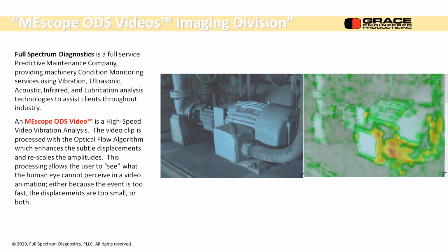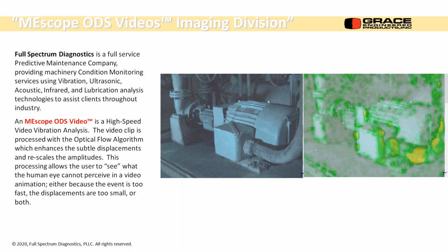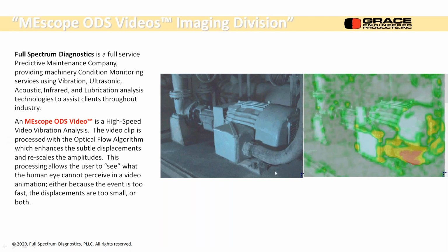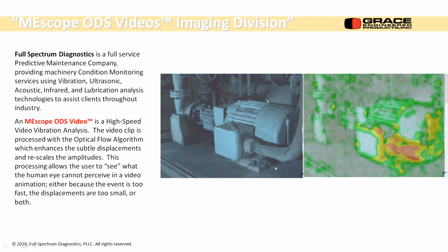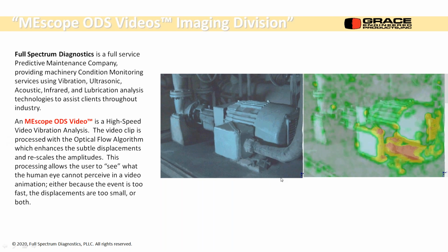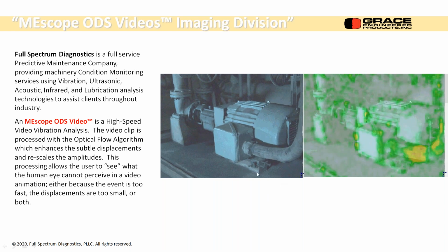So here you can see there's some type of problem in the machine. It's moving awkwardly. What it turned out to be, I'll give you a short version of this, is there was a problem in this foot of the motor, or the structure under the foot. This base plate was grouted in, a big C channel or I-beam channel around the outsides. They pumped grout in.